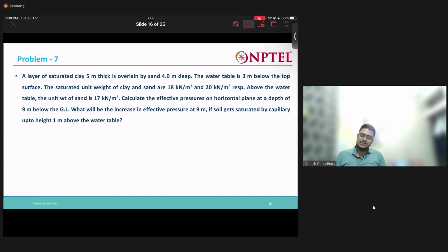So why is effective stress very important to us? Because all the strength-based or failure theories, such as in the shear strength chapter, the Mohr-Coulomb theory, mostly need us to consider effective stress, because the main stress is mobilized at the contact forces of the soil grains.